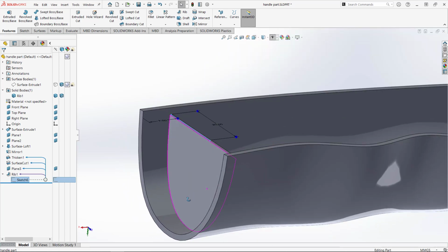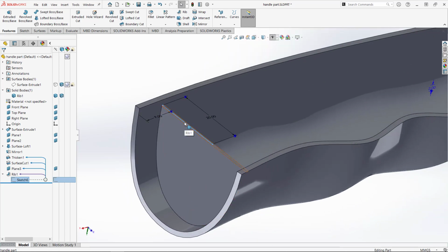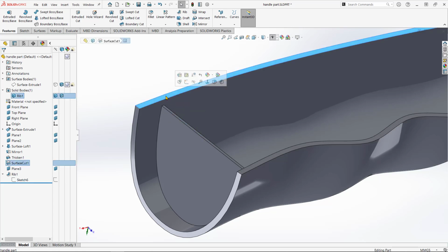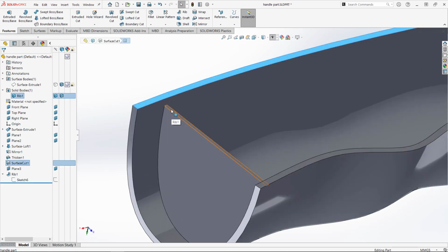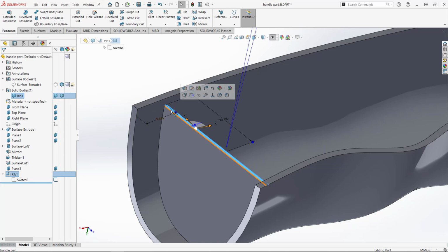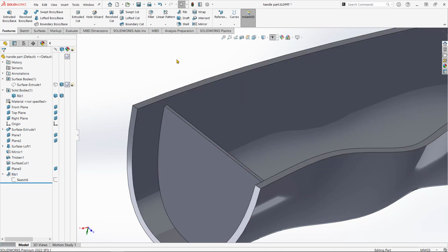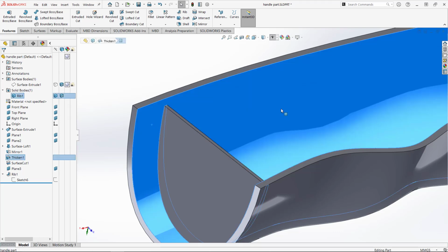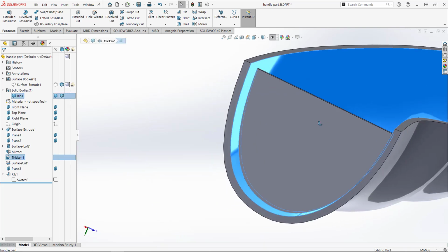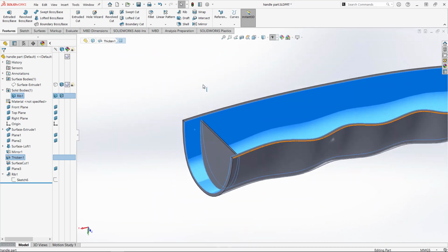So it's important that the planes that you create your rib sketch on are either in line with the top of the part, or, as we've done here, down inside the part by some distance. If they are up above the part, they will fail. The system can't create a rib unless at some point away from the rib it encounters the inner face of the part somewhere.